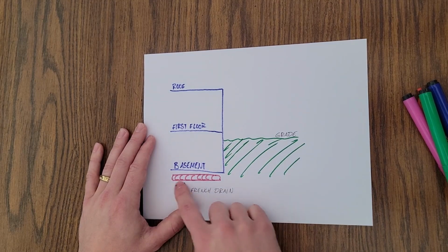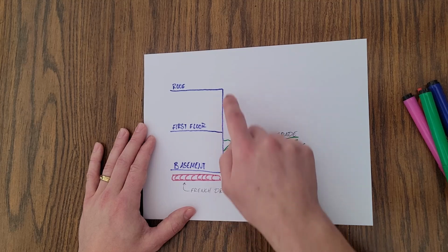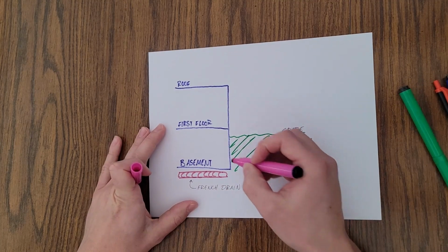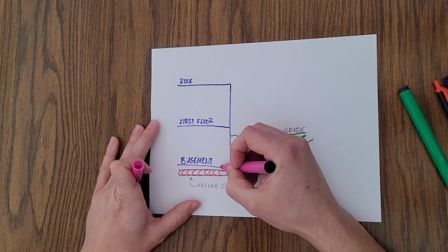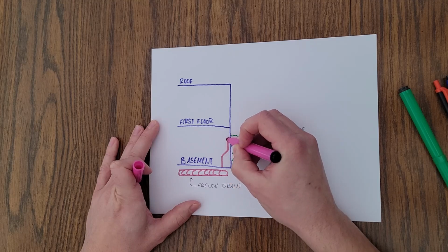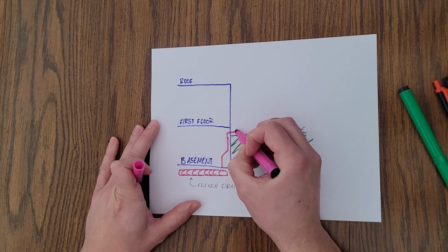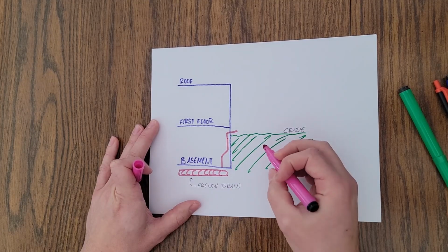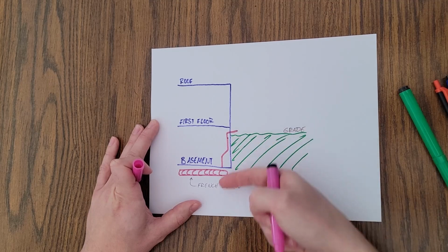We want to go from our French drain that's below the slab out through the exterior wall and then past the roof. If we route our piping, I'm thinking the design is going to look something like this. We're going to go from the slab, then have a 45-degree angle up towards the wall, then go up along the wall and make a 90-degree angle out through the exterior wall. And we're going to make sure that this piece of piping here is sloping back into the house.